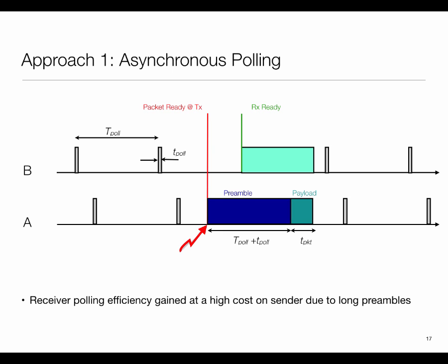Now, you might say the transmission becomes very expensive, but these are rare events. So I'm better off, whenever the rare event happens, to send out a long packet, as opposed to keeping the receiver up for longer periods of time. Receive can be more expensive than sending, so this kind of approach wins out.